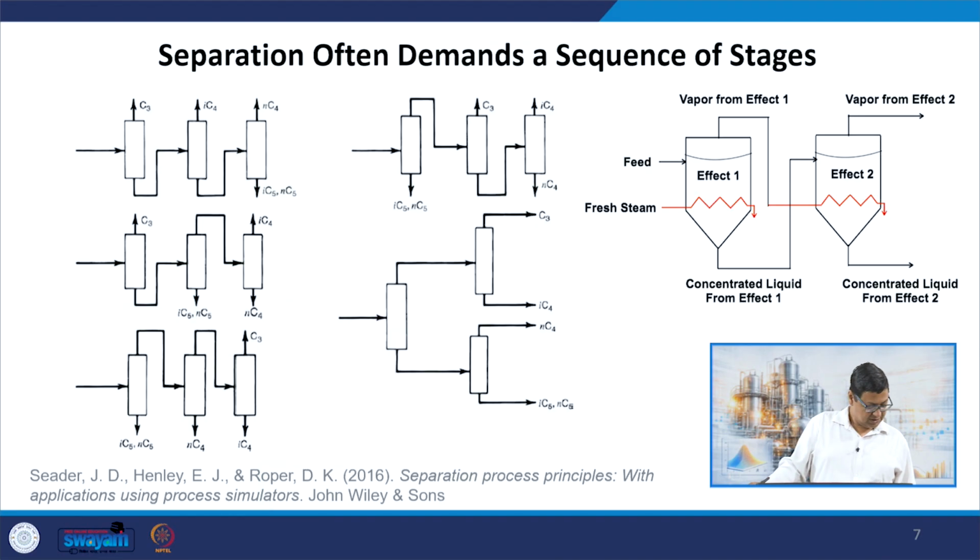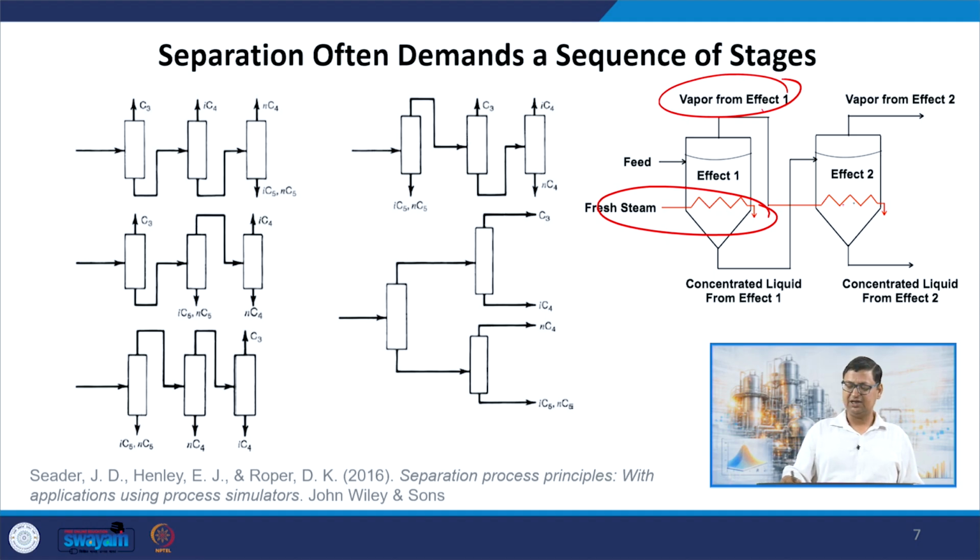Okay. So, as you may expect, that separation is going to demand energy, and in fact, when we were doing these evaporation processes, we have found that if we are using multiple effects, that in principle is more effective, because in the case of evaporator, let us say I can use the fresh steam only in the first effect, and whatever vapor that is coming in from there, that can become the heating medium of the subsequent effect.